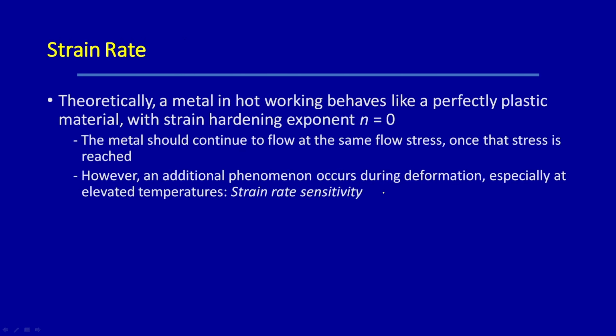So now that is temperature. What about strain rate? If you can apply high strain rate, you can deform faster. If I apply low strain rate, you deform slower. So strain rate is very important. But if I apply a lot of high stress, the material may fail, break down. So therefore, we should understand what is the effect of strain rate on the material behavior.